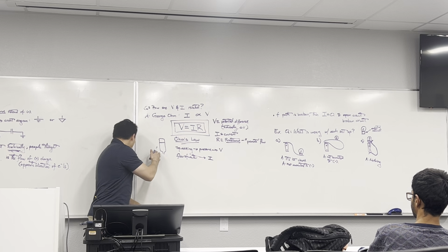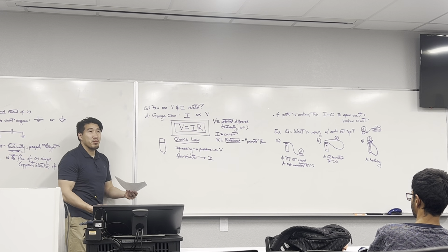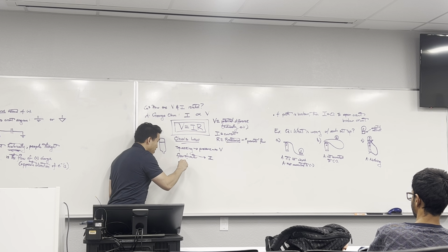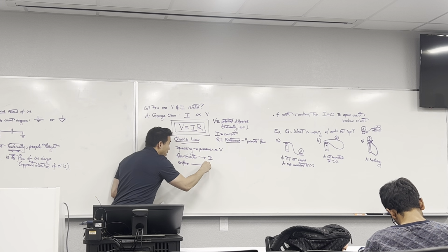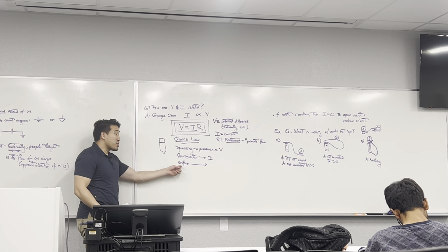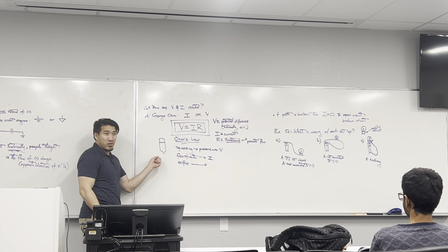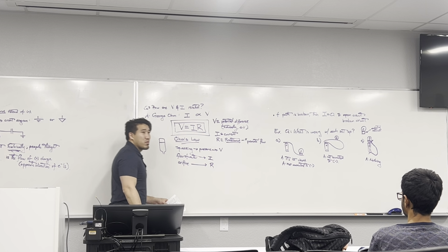Well, in our water bottle scenario, there is actually something preventing the water from coming out, and that is the opening, or what I will call the orifice. This orifice restricts or limits how much water can actually flow through. This would be analogous to the resistance R.